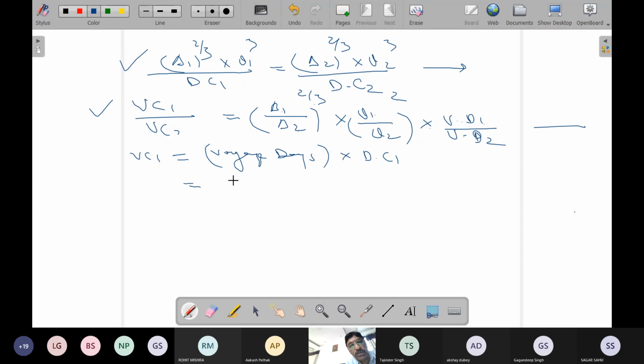Voyage days is nothing but the voyage distance, so voyage distance 1 divided by V1, divided by 24. This is the voyage days. The distance divided by V1, you get the hours, divided by 24, you get the days. So this is voyage days multiplied by DC1. This is the voyage consumption. So I give it relationship number 1.